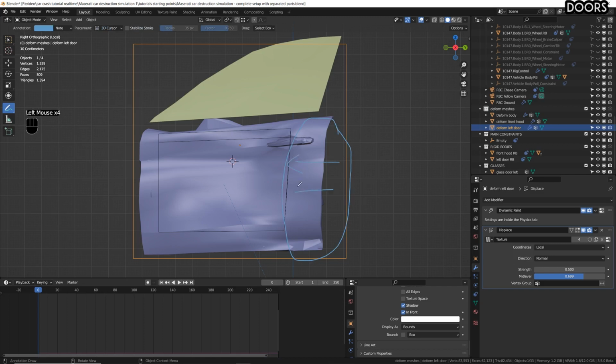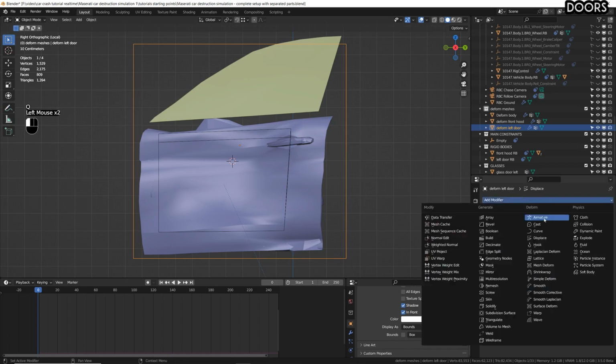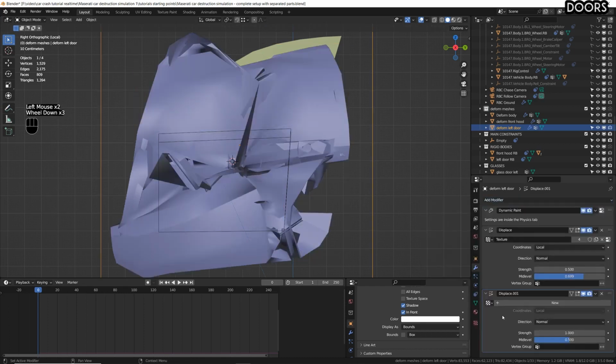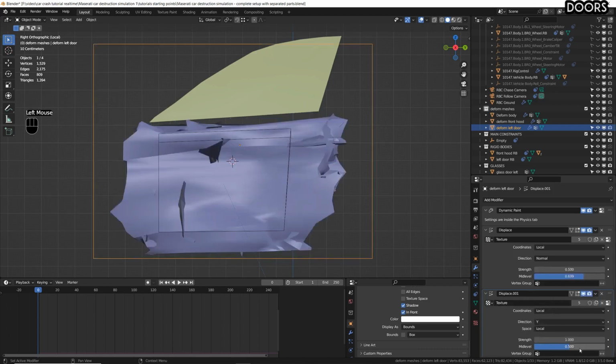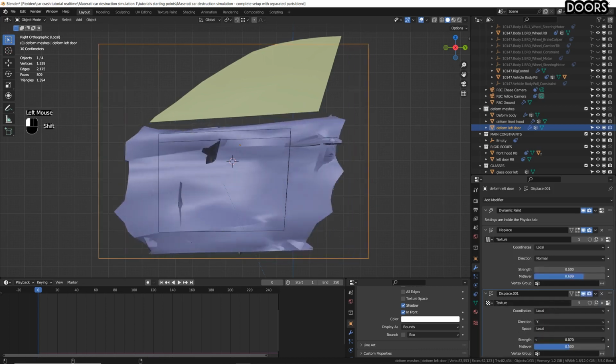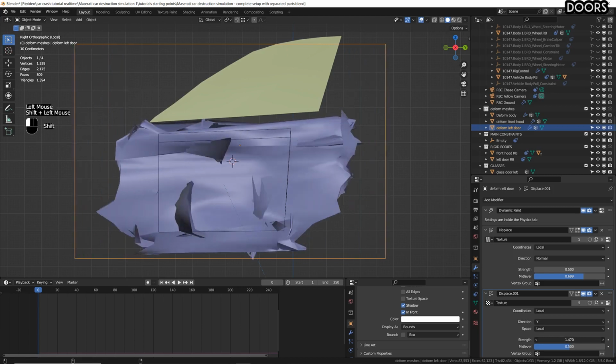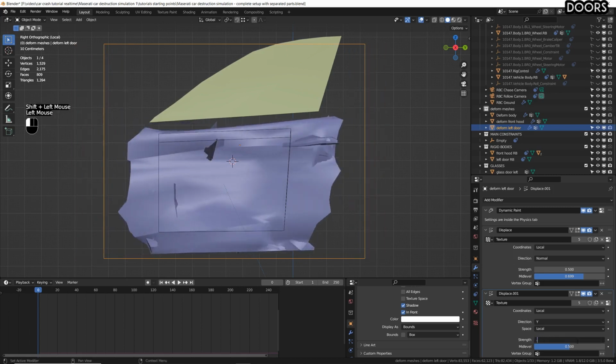All right, now I want to give a secondary displacement for pushing this geometry in this direction, more or less, like this, because this part of the door, of course, is going to hit everything it meets on the road during an accident. So let's give another displacement, add modifier, displace, texture, is going to be this one. So for the direction, I'm going to change this to the Y direction, which is as before, this direction here. If you try to tweak it, you can see what this is doing. So something like 0.5, don't exaggerate.